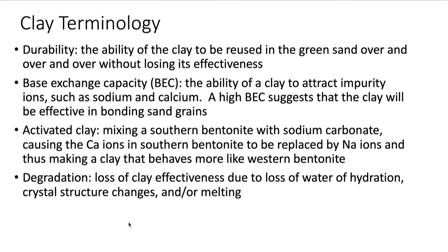Okay, so lots of different terms. Durability: green sand gets used over and over. So the durability is being able to keep on absorbing that water time and time again without losing its effectiveness. Otherwise, the clay is said to die. It's still there, the platelets are still there, but they don't have any more bonding capability.